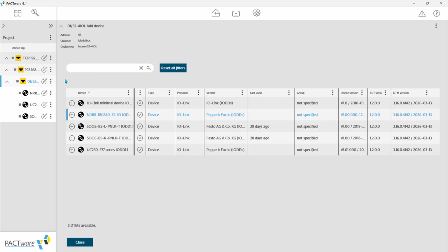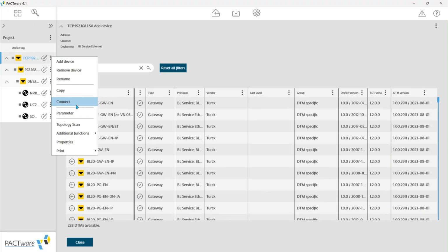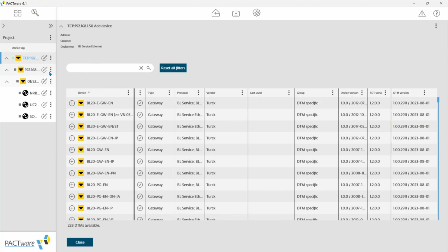Now at this point, definitely make sure, which you should have already made sure, but just in case you forgot, make sure you have power. So these power leads and the switches on, make sure you have power going to your input output module. You probably would have noticed that a while ago, that you weren't getting communication. So at this point, if you have power and connectivity, you're going to go down this line, and we'll start at the top. So you click those three dots and you'll click connect, and we're going to go down the line and just do connect, connect.